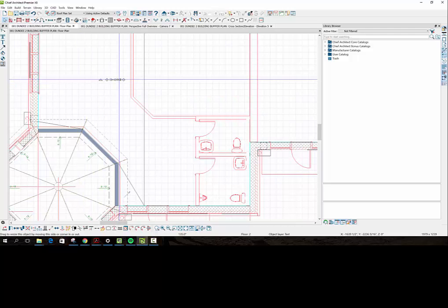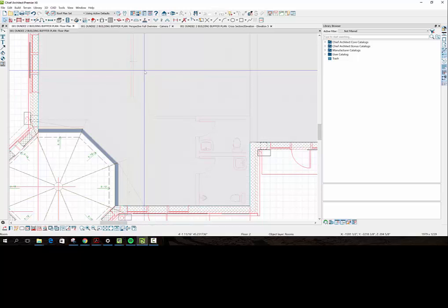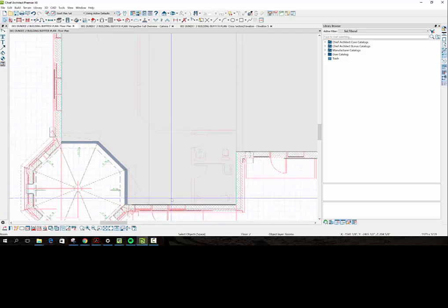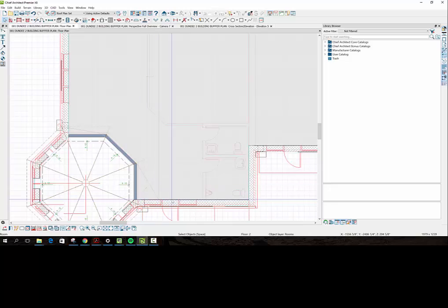Kind of a small arrow, but whatever. Control, slide it into place there. So there's a high point. Water going this way, just traveling along this geometry. It's not getting trapped there. Here it is. And then going around to the horn there. So we may not even need the scupper. Yeah, we might not even need the scupper because we're getting rid of the water there. This is coming here, and we'll just bring it over around to this one.